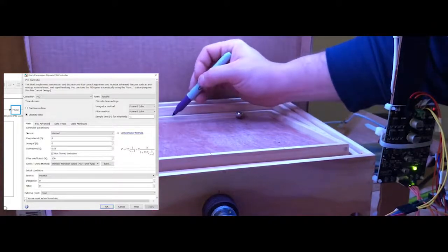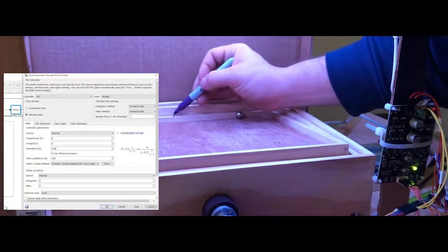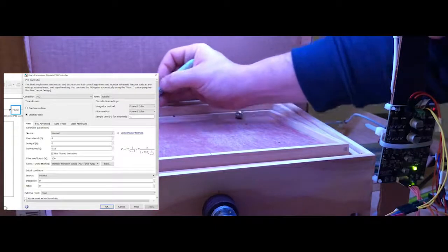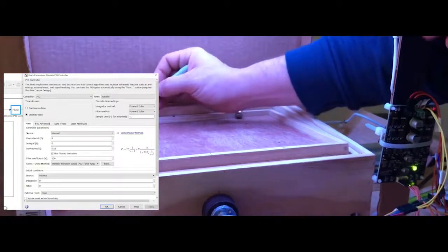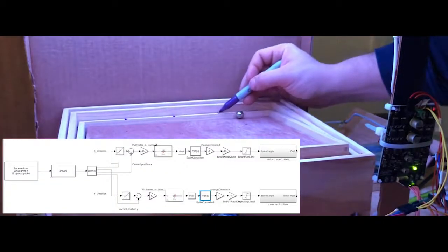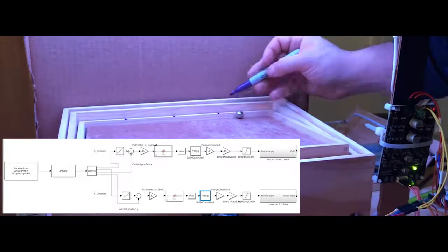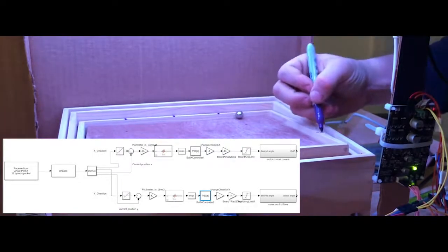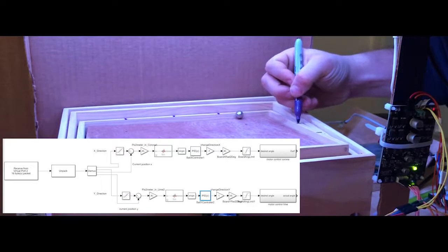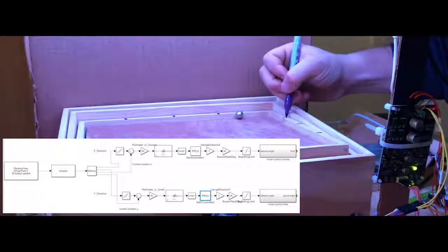And so we set this proportional gain fairly high to have high response so that the motor would move the board fairly quickly. And our derivative is fairly low. These go into the actual microcontroller.